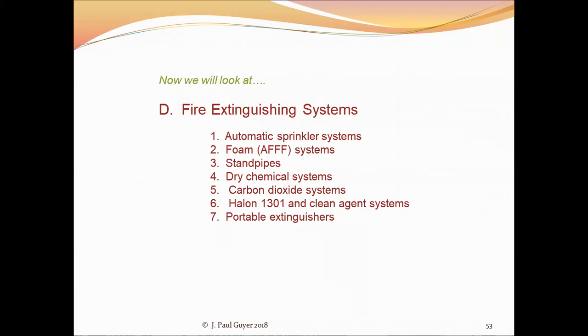Then the Halon 1301 is another gas type system, originally developed a few decades ago to protect computer rooms, electronics equipment rooms, things like that, where you have high value equipment and high value data, and you don't want an automatic water sprinkler system to go on and spray water all over this expensive equipment and ruin it and ruin the data. So Halon gas systems were developed, and they remove enough oxygen from the environment to suffocate the fire,